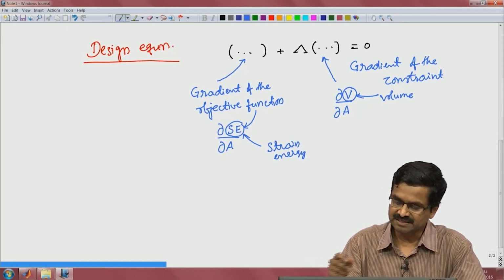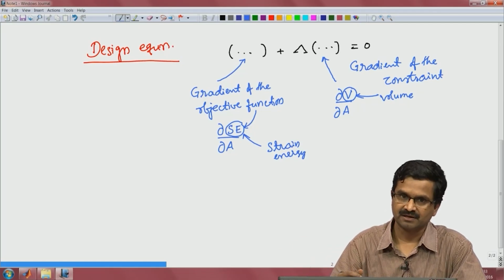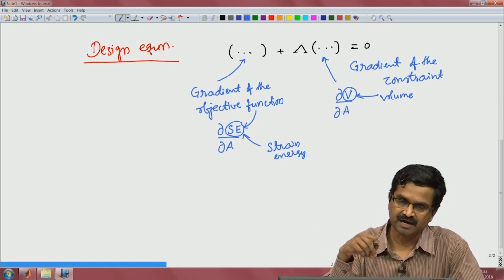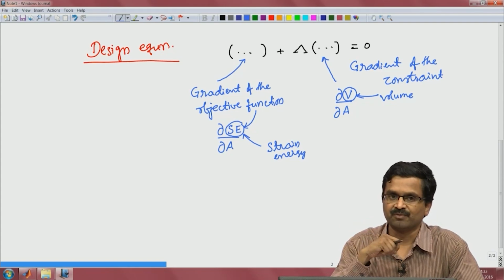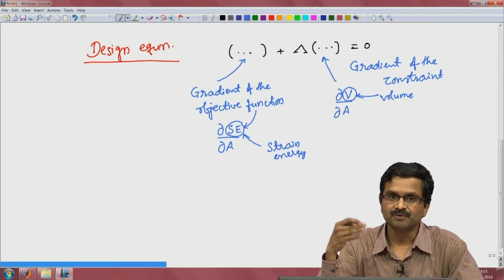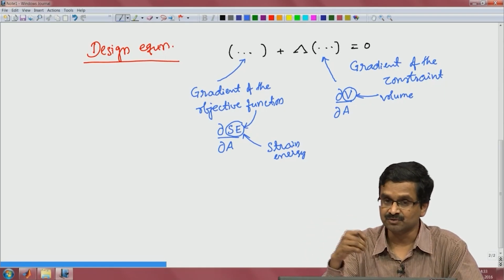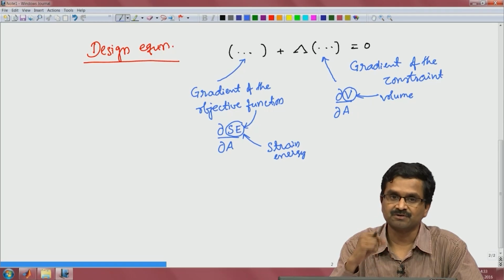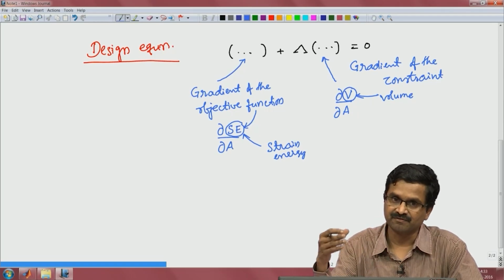So, basically that is how we solved for A of x in this problem, substituting that back into the equilibrium equation. In general, that may not be possible, that is, interpreting that u prime equal to constant and using that in the equilibrium equation and solving for A